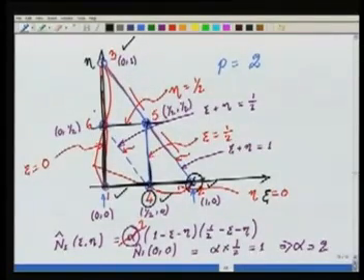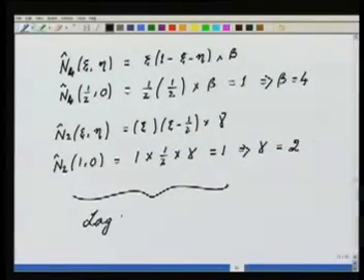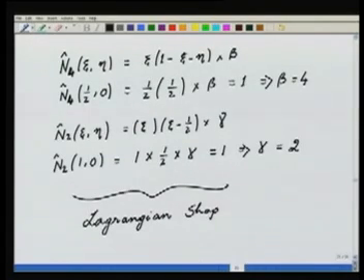n6 is very easy. n6 will be 1 here, 0 along this line and this line. So it is 1 minus psi minus eta into some constant, that is equal to n6. So this way I can construct the quadratic shape functions, all the 6 quadratic shape functions. And what I have done is essentially an extension of the Lagrangian definition to 2D.